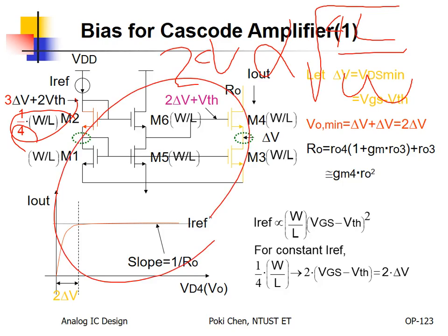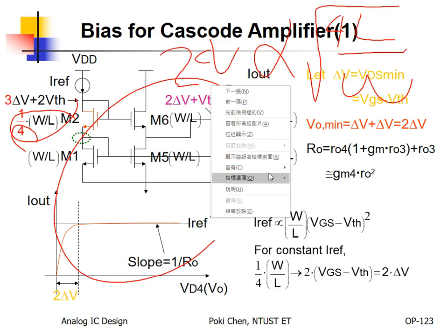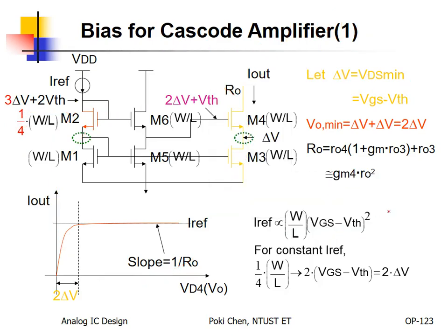But I need to remind you, according to body effect, here usually we design longer L, 5 to 6 usually than 4. That is in practice. So the first cut for your own design, 4 may be good enough.